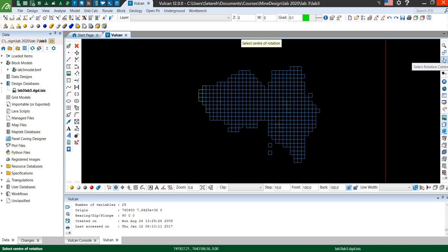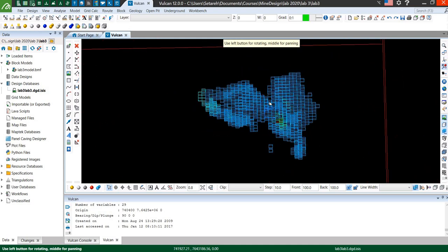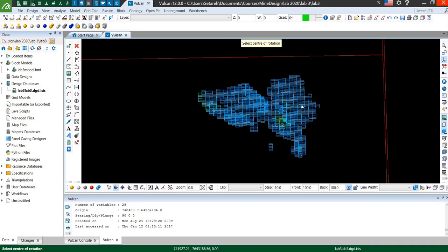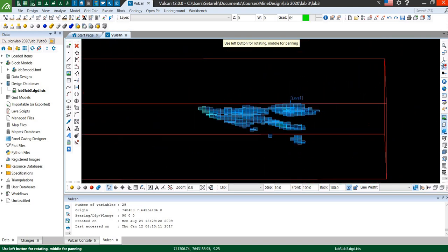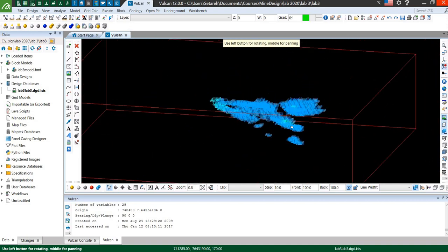If you go to selecting rotation center, right click, it is going to rotate. One of the shortcuts for the rotation center, instead of clicking the rotation center, on the keyboard you can use C as well. So if I escape out of the rotation mode, I click on C on the keyboard, it will get to the rotation center and I can select and rotate.